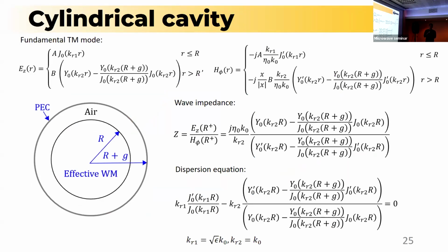But at the end, when we got the lambda over 4 condition, we had the ideal case in which we have a plane wave incident on a perpendicular boundary. Now we don't have this ideal condition, we have a circular boundary. So analytically we are getting these Bessel functions and the roots are slightly changing from lambda over 4.